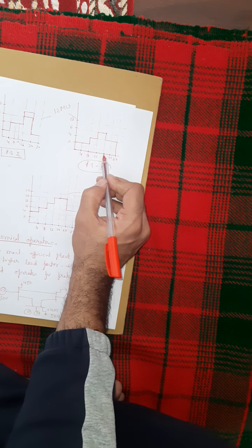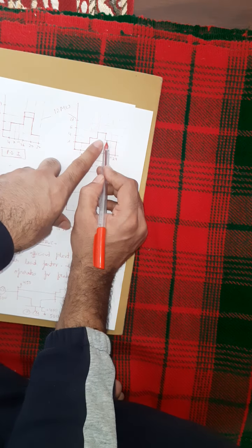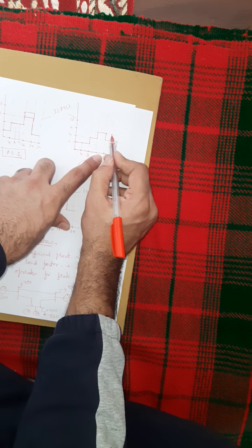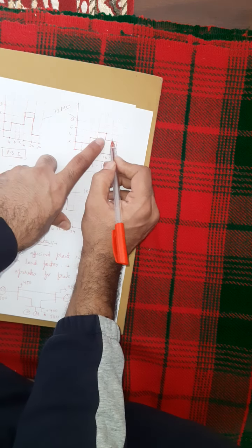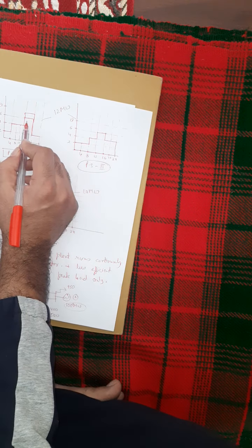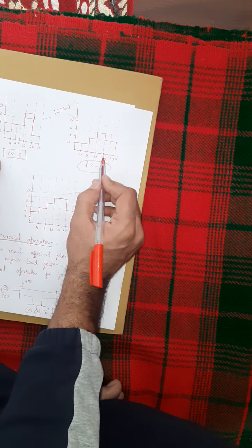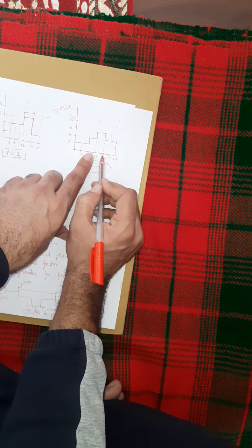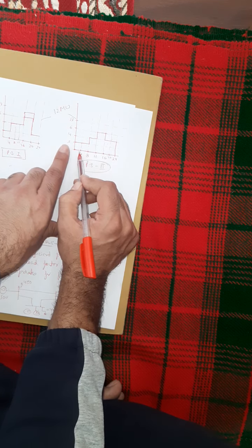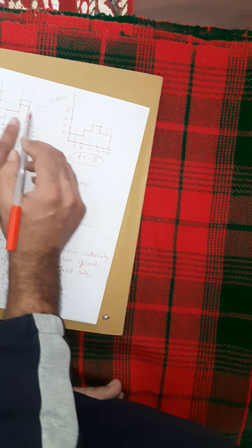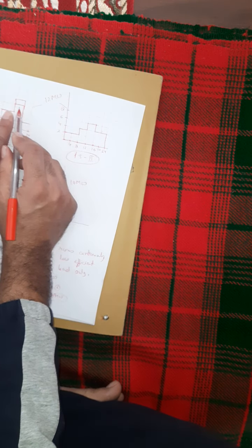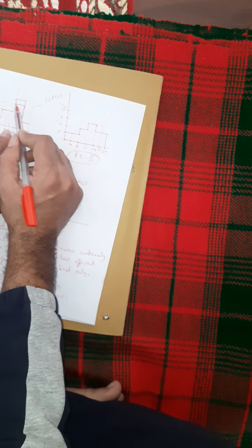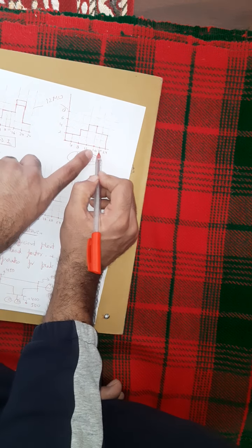Since this power station is connected to this power station, you can see that from 1600 hours to 2000 hours, the load here is 4 megawatt, but the maximum capacity is 6 megawatt. So this power station has 2 megawatt of reserve capacity. It can supply 1 megawatt of power to this power station from 1600 hours to 2000 hours. It cannot supply between 1200 and 1600, but before 1200 hours and after 1600 hours, it can supply power to power station 1. So the 1 megawatt of extra load on this power station can be supplied by this power station.